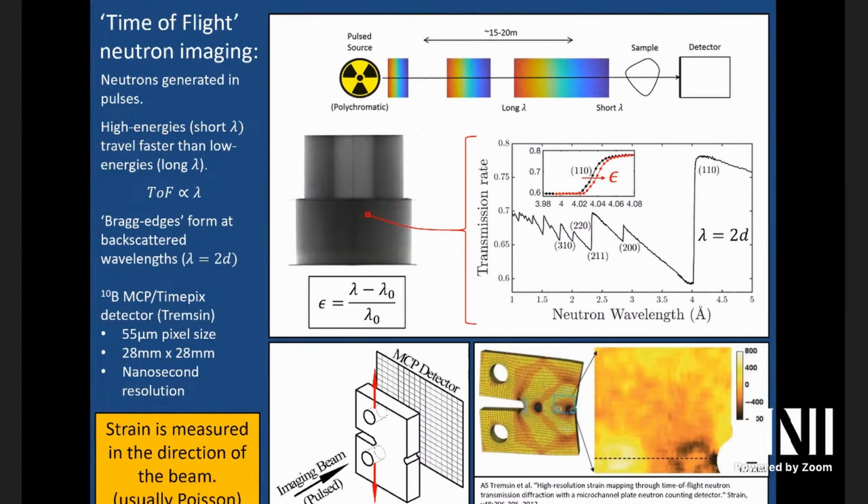Yeah, I mean, probability distribution, which you call texture. There's two versions of it. There's one version where the whole sample has a texture, and that's probably pretty realistic in a lot of cases. What that means is that every Bragg edge has a different shape from a different direction. You'll still see the Bragg edges at the same places, but every time you look in different directions, it'll have a different height and different shapes. And so it just makes the physical process of fitting something to that curve and getting something consistent hard.